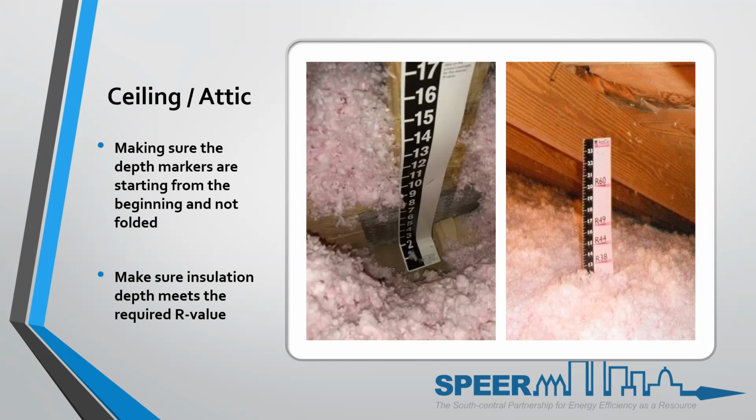I have seen it in the past. If they're done afterwards, if they're not installed before sheetrock is installed in the ceiling, if they're done after sheetrock's installed, it's easy to curl it down and then staple it. That way they don't have to blow as much insulation and it looks the same.